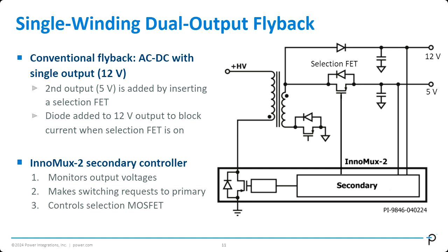As you can see over here, I'm using a single winding on the secondary side for 2 outputs. For certain cases, we have to use either stacked winding or independent winding on the secondary side. Over here, I'm only using a single winding because I want to show you what the voltage on each node is. And with a single winding, it's just easier, and it helps us see more easily where the current should be directed.